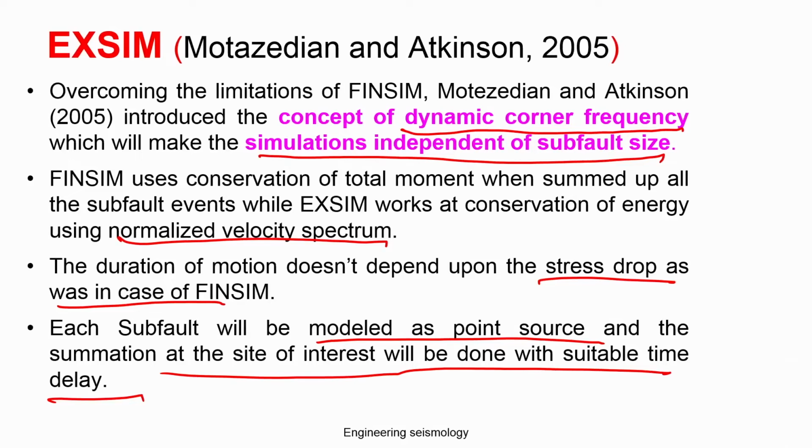So, as of now the EXSIM models are the better ones, but below magnitude 7, EXSIM and SMSIM do not make much difference. Above magnitude 7, you need to use EXSIM, depending upon the place. Even now you can categorize: if you want to use simulation at peninsular India, where you expect a moderate earthquake, below 7.5 or 8 magnitude, you can go for the SMSIM. Mostly 6, 6.5 earthquakes you can easily create with the SMSIM model.